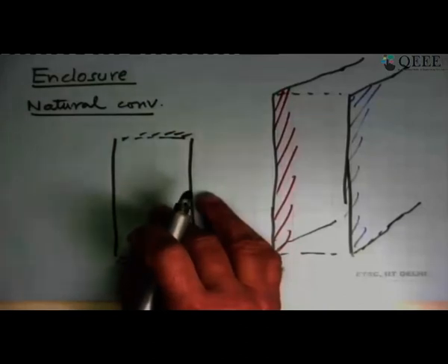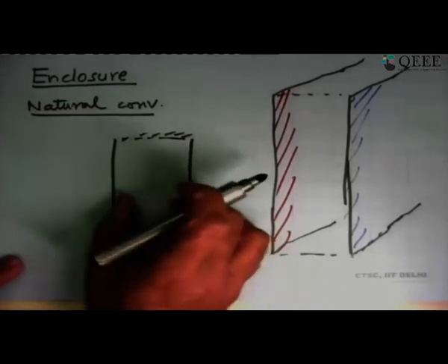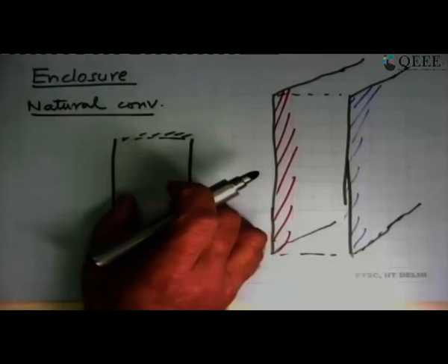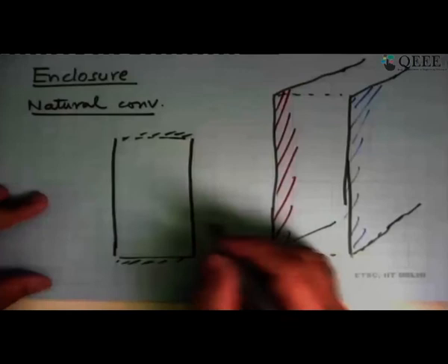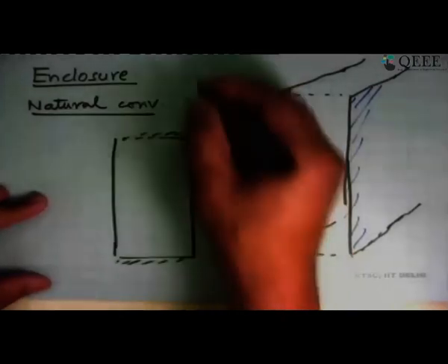But when you have a slightly larger space and natural convection sets in, then the overall conductivity of that air layer is much better than when it was still. Then it doesn't do such a great job of being an insulating layer. So this is something you have to worry about. A similar thing is done in many cold conditions where you have what you call double glazed windows.